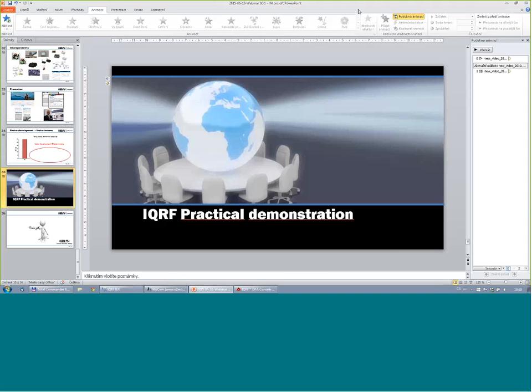10 temperature sensors. Then you can send Selective FRC only to the temperature sensors, and you can get 2 bytes of information from all the temperature sensors in one communication. So basically, if there are 20 nodes, in 2 seconds you will have the temperature information of all the temperature sensors. We will show this in a few minutes in a practical demonstration, so maybe it will be more clear.